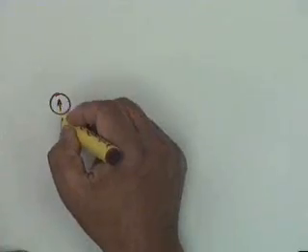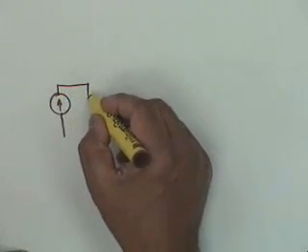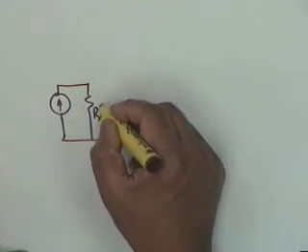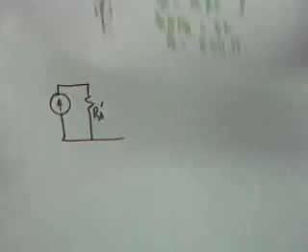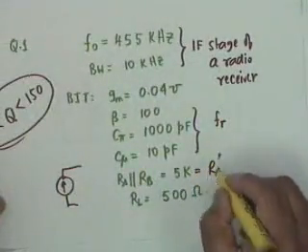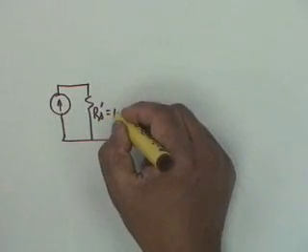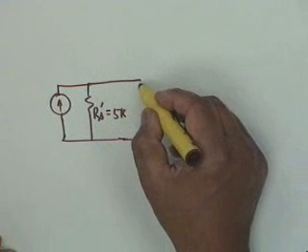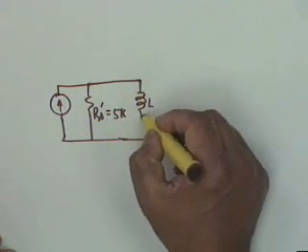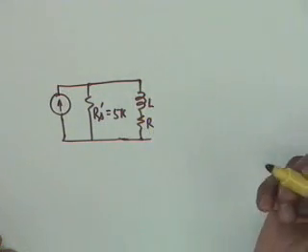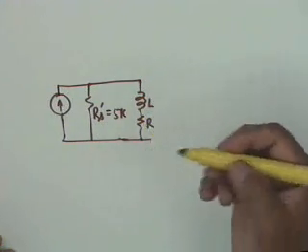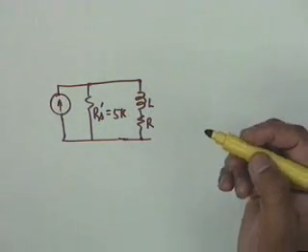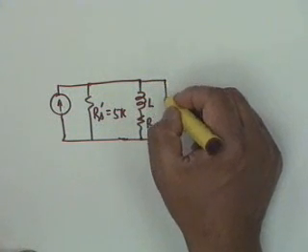The circuit that we plan on, it's almost given, everything is given. It is given that this resistance, RS parallel RB, we call RS prime. This is given as 5K, then you connect the tuned circuit here. It's an L in series with a resistance R. We had to use capital R because Q is specified to lie between 10 and 150. That means you have a choice of Q. Let us see what Q we shall choose.